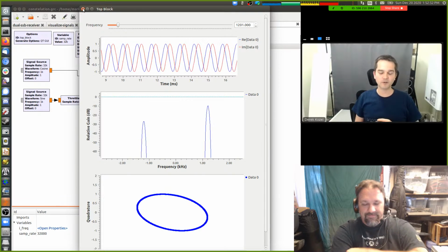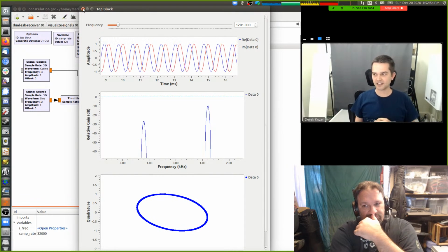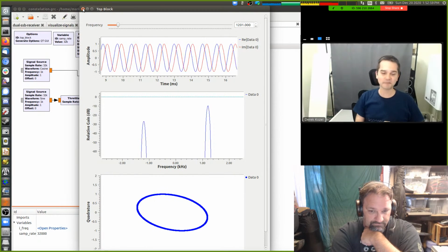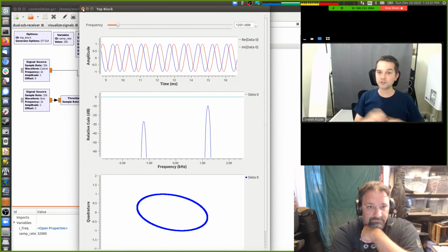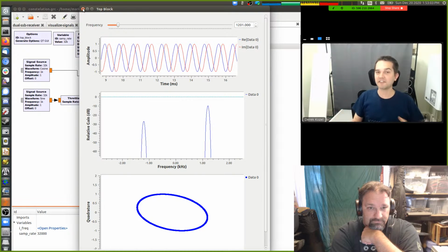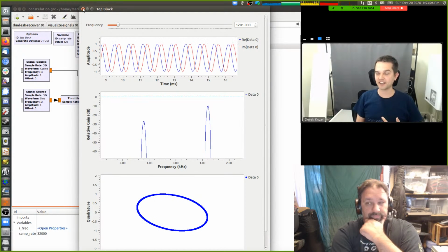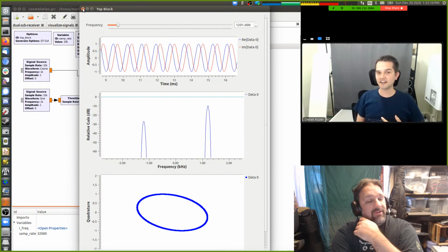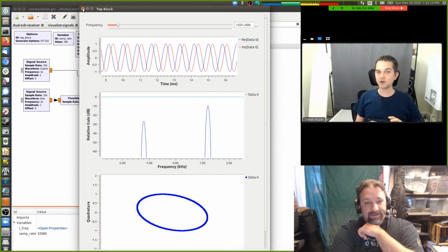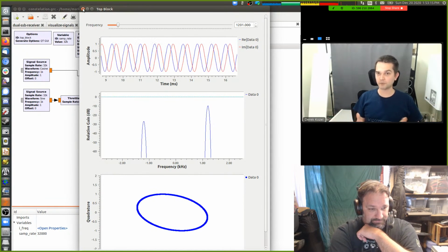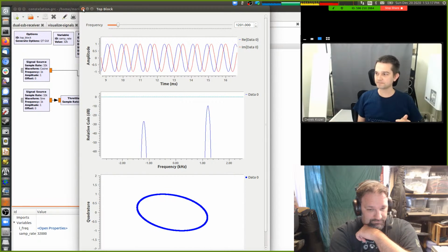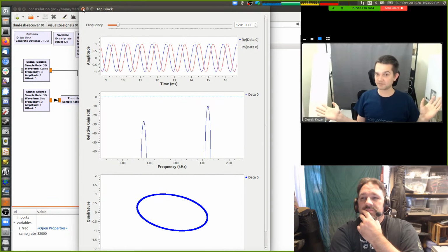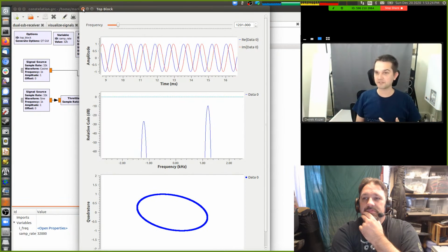Whereas if you used a quadrature DAC and a quadrature mixer... Sure. You wouldn't be wasting power twice. And you would not have to have these filters at the IF, which are fairly narrow filters. And hard to build. A pain in the butt. So by using quadrature sampling, we avoid all those filters, because we are just directly producing the right value because we've done math on it.